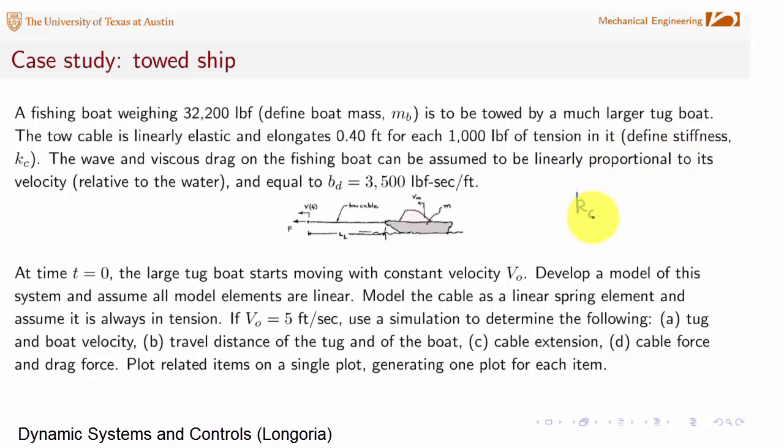Since you can say, okay, C is approximately the change in the force that you put on it over how much it changes, right? That's your basic definition of stiffness. As the boat's being pulled through water, it has some viscous drag, and we're going to assume that we're given a reasonably good estimate of damping on that, and we'll model it linearly. Could always change this and look at nonlinear type damping, which is probably more realistic, given that this is a flow around a bluff body and a fluid.